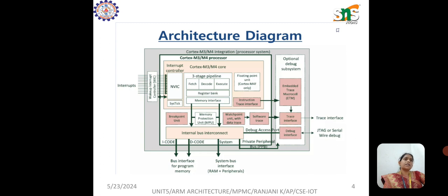ARM architecture is an advanced reduced instruction set. It is a 32-bit RISC processor, and it has an arithmetic logic unit, a Booth multiplier, a barrel shifter, a control unit, and a register file. In detail, the ARM processor has other components like a program status register, which contains processor flags: the Z flag, and status flags V and C. The mode bits also exist with the program status register, in addition to the interrupt and fast interrupt disable, and a priority encoder.